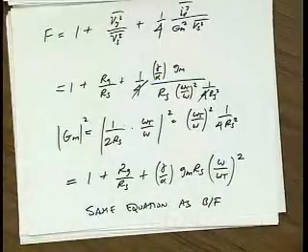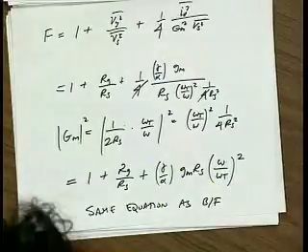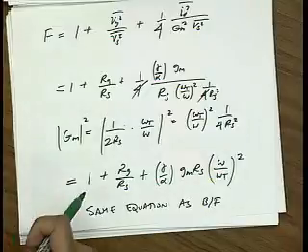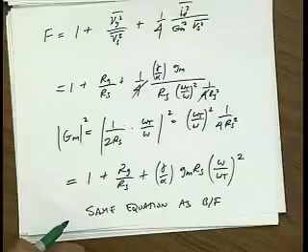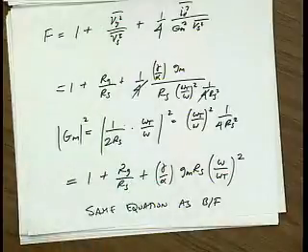In other words, we got lucky. The fact that we degenerated our device produced a real input impedance, which is very convenient for matching, and it didn't increase the noise. That means that the F-min of the device is exactly the same as before. So to answer your question, we don't need to redo the calculations. It's all the same.